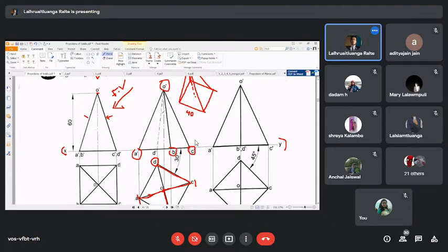All right, so that is how we are going to annotate hidden lines, or basically lines that are behind us, but if it had not been behind this, we would still be seeing it. So that is why we are making the line with dotted or dash lines over here.